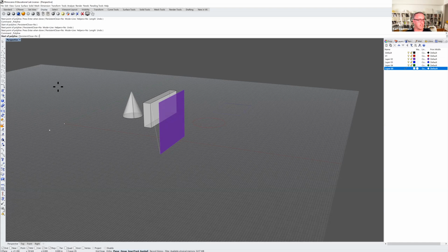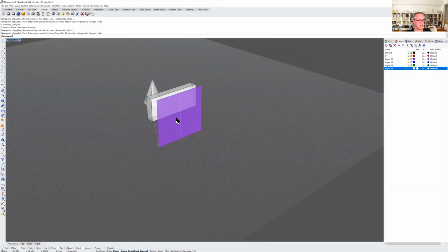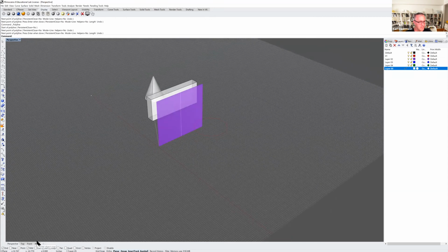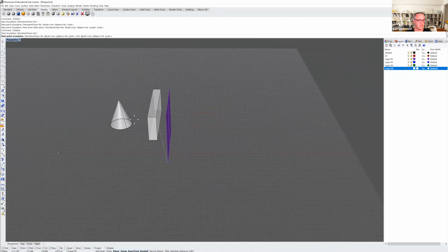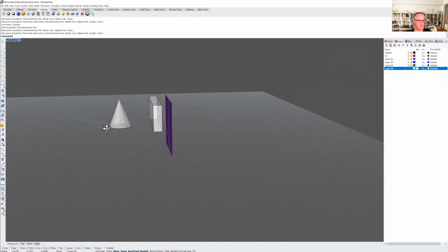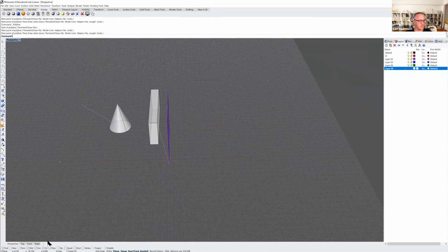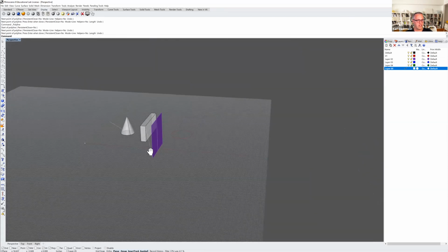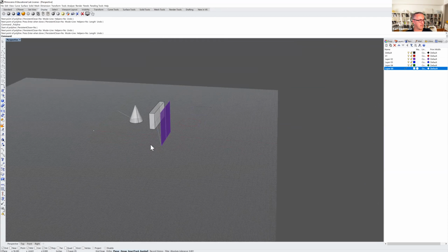as you're doing it. So like mid is on, right? Well, we should be able to find, there's the midpoint of that. And that's perpendicular. Right? And so if you're trying to, sometimes center is not helpful, but sometimes it is. And so you might be able to find the center of an object. Right? That just snapped to the center of the object, which is there, but sometimes it might get confused. And so maybe I'll turn center off until I need it. All this make sense?